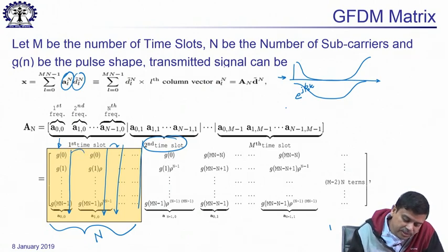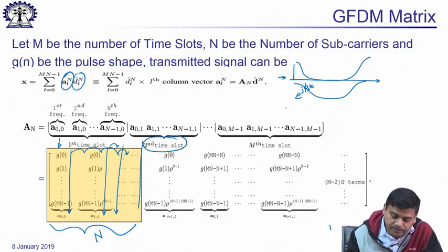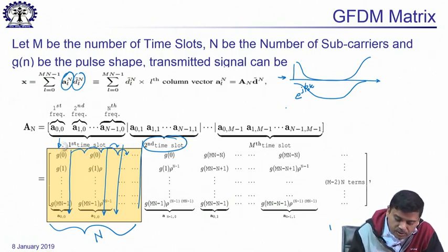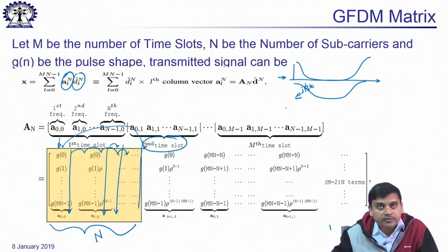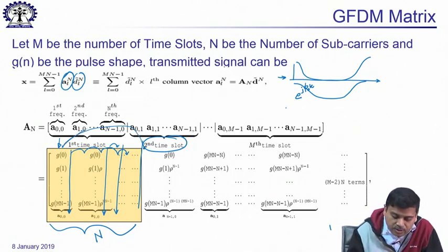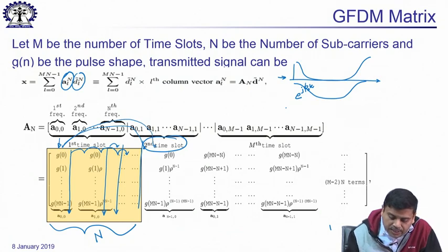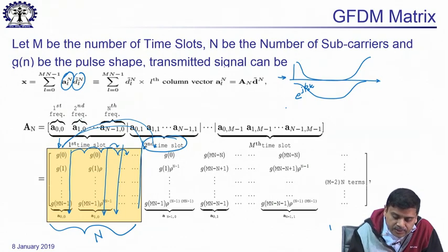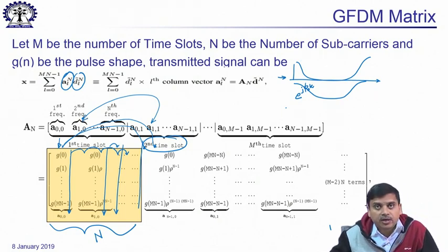These are frequency modulated Gabor atoms of the primary atom. From the first column over here to the first column of the second slot, it is the time shifted version, and from the first column to this column over here, it is time shifted and frequency shifted. If we compare the second frequency over here with this one, these two have the same frequency shift, but there is 1 unit of time shift difference between them.